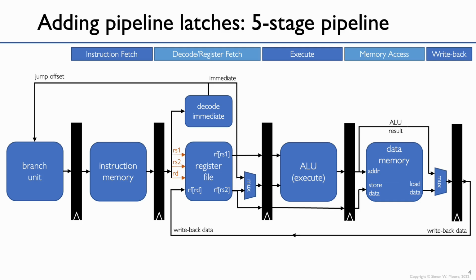So instruction fetch begins by fetching the instruction from memory. And we then move on to decode, execute, memory access, and finally write back. I suppose I should have drawn the write back box starting at the last D flip-flop, but there just wasn't quite space. So I hope you'll forgive me.